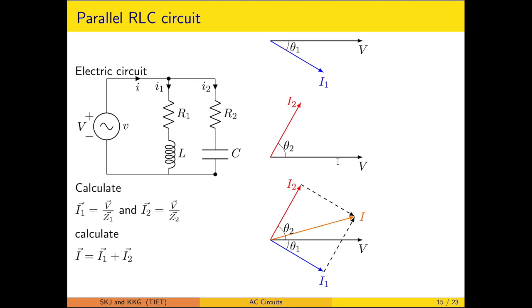However, we can easily do it using the concept of superposition. Basically this is the concept of superposition. So we are redrawing the phasor separately for the RL branch. In that, the current is coming out to be lagging. For the RC, the current is coming out to be leading, and that is marked. Now superimposed, that will be the arrangement, and the net current is decided by the law of parallelogram and so on. So that is giving you the value. In this particular case, it is coming out to be capacitive behavior.